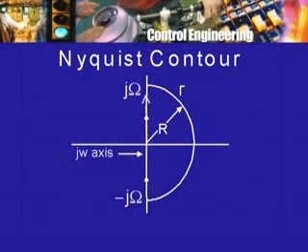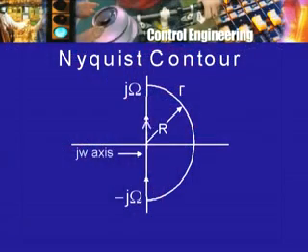Now, I can choose it to traverse in the counterclockwise sense or in the clockwise sense. Normally, I would have chosen the counterclockwise sense because that is the preferred direction of rotation when we talk about phasors and so on. Again, historically, and for a reason that you will see very soon, one chooses this direction going upwards from the minus j omega point to the plus j omega point, and therefore in the clockwise sense to complete the contour we will travel it this way.